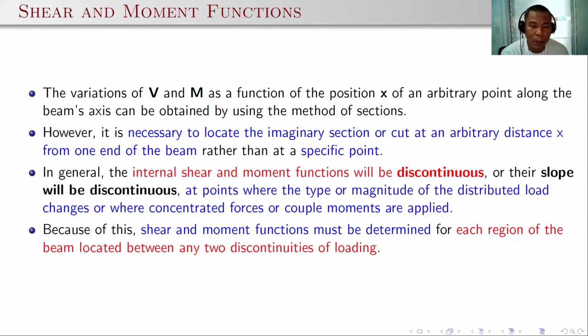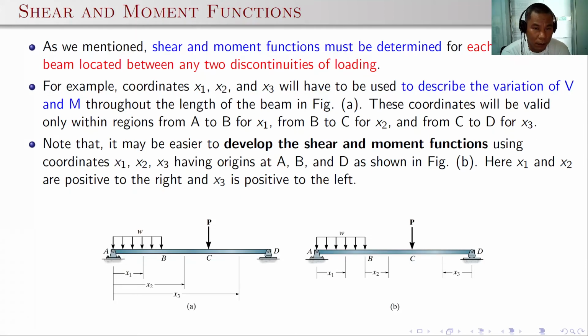The shear and moment functions must be determined for each region of the beam located within two discontinuities of the loading. So remember, if you find some discontinuities of loading, then you have to define your function within that region only. Okay.